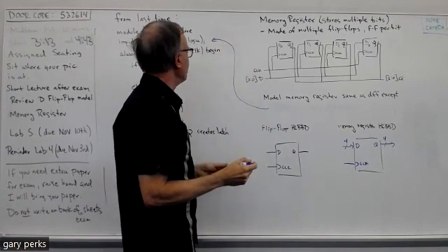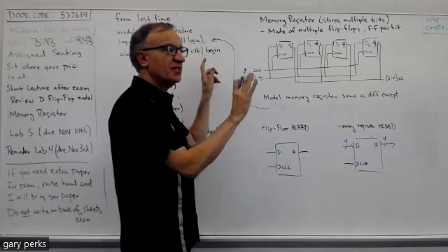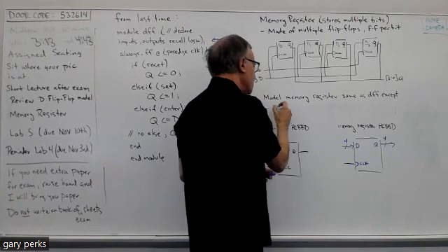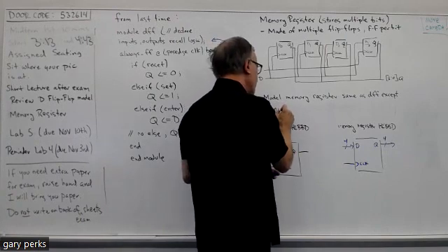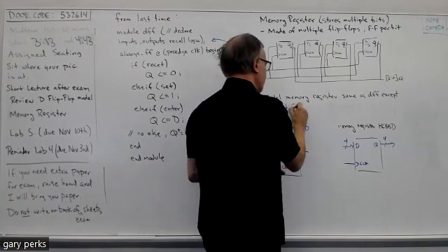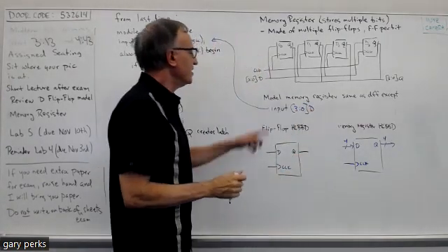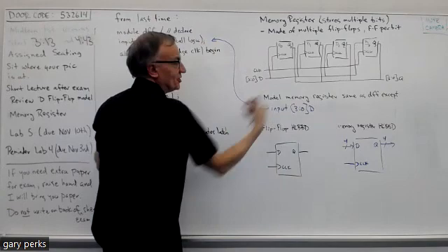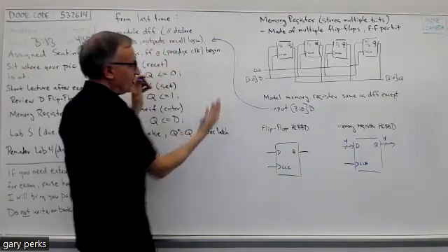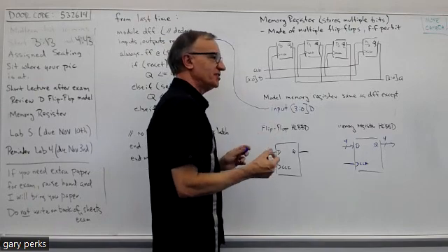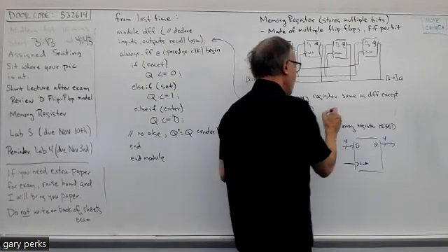One edit you would have to make is to declare your D input as 4 bits instead of a single bit. So you would have input [3:0] D. For a single bit, it's just input D. But all you have to do is take the same code and declare your D input as 4 bits instead of a single bit.